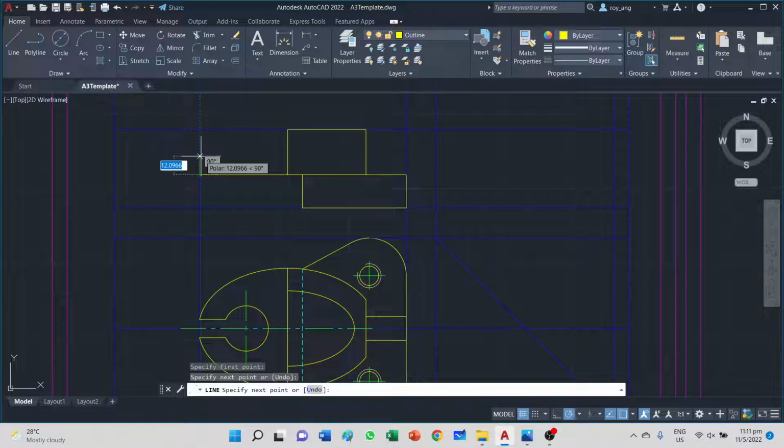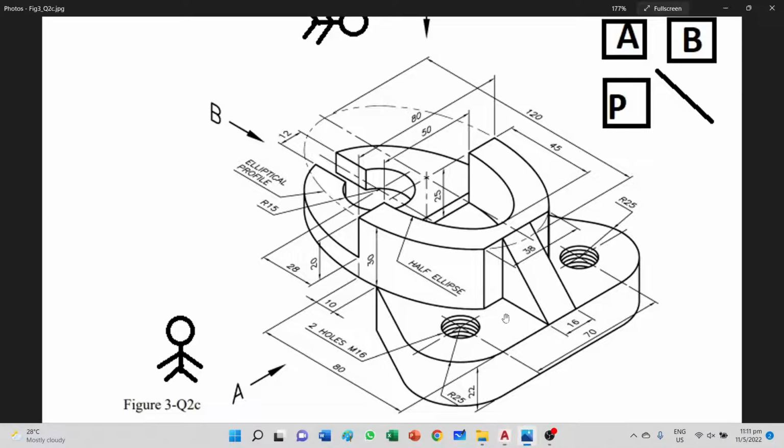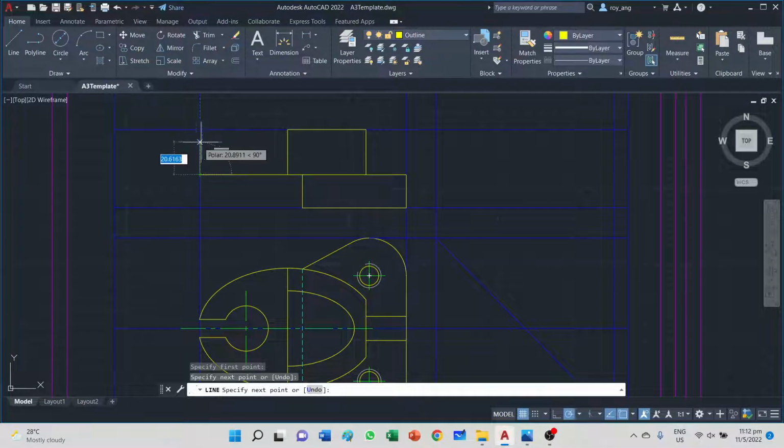What is the thickness of this? Right, it is 10. How did I get 10? If you look at this, I'm now here, I'm going up, and I have to move up a certain distance, and I don't know what this thickness is, but if you look very carefully, there's one number here which is 30, the second number is 20, so it's 30 minus 20, you get 10. Okay, you bring it down, and so I'm going to go up by 10, and I'm going to go across.